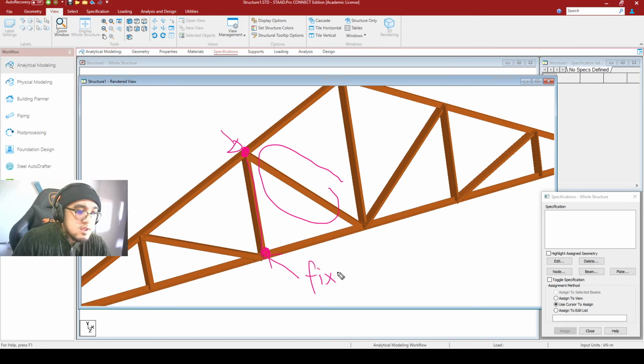So with that being taken into consideration, guys, we are actually allowing our members right here to be subjected with a very small amount of a moment restraint, or let's say a bending moment, I should say. Kasi nga finifix mo siya dyan, no? So, ayun. So in our design, guys, if I am to be the engineer, or let's say that you will be the structural engineers very soon and you would be listening to my advice, I say that it is logical for us to have at least 1%. So let's say we would be giving our web members 1% of the capability to hold moments because of the presence of welding.